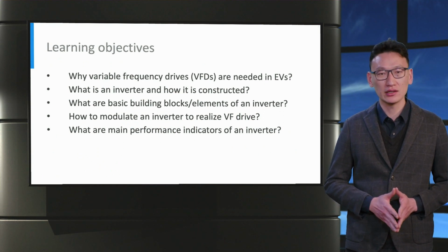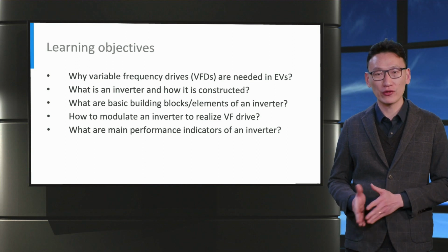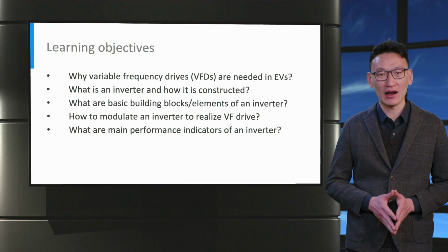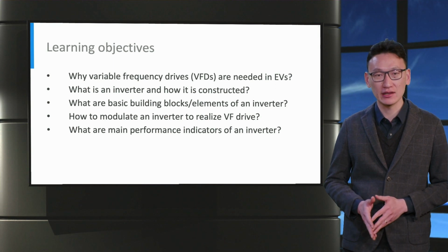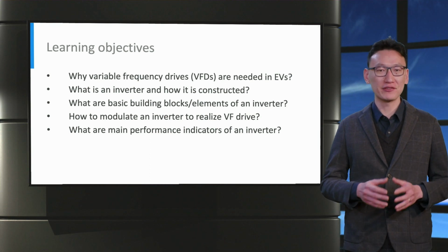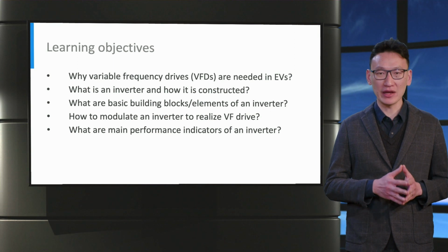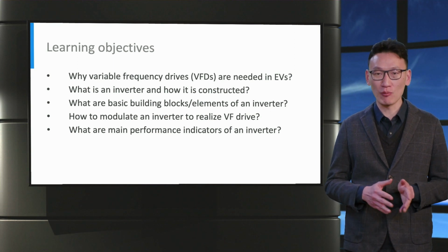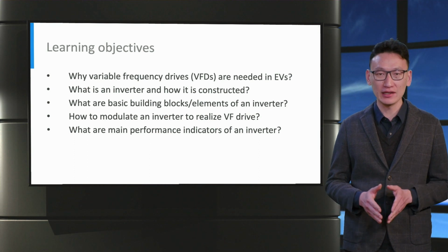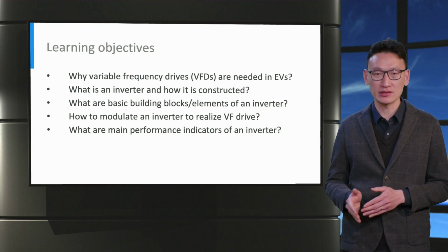First, we take a look at variable frequency drives, or VFDs, and understand why they are an essential part of EVs. Next, we understand what inverters are and how they are constructed. After this, we look at the elements of an inverter, their modulation to achieve a variable frequency drive, and finally, the main performance indicators of an inverter.